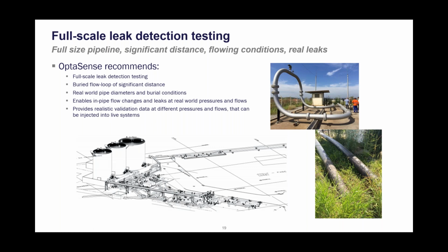Full-scale leak detection in a pipeline, in a buried pipeline, doesn't come easily. There's not many places in the world you can go to carry out this sort of work. You want somewhere that has got a full bore pipeline, or at least a representative bore size. You want to be able to change pressures, you want to be able to change flow rates, and ideally change the product from a liquid to a gas. We think these elements are all required for true validation.